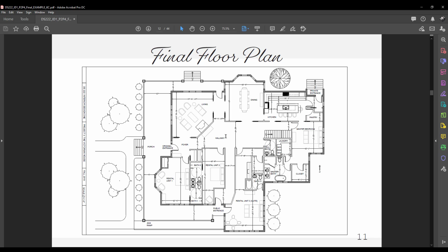Make sure that you rotate all of the text. So you don't want people to be turning their head trying to read the room labels, for example. So make sure that those are all rotated, and you can simply rotate one and then use match properties in AutoCAD, MA, and that will do it for you. So you don't have to rotate the dimensions, but just like the room labels and that type of thing.